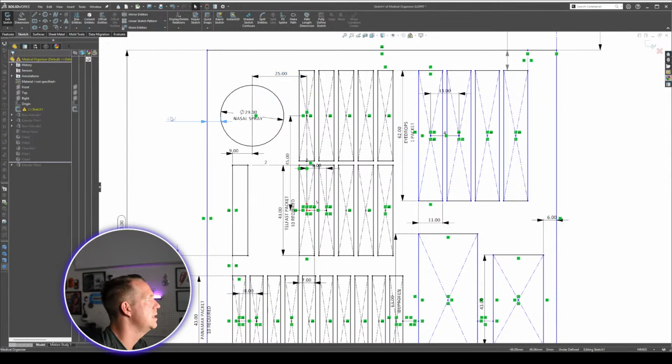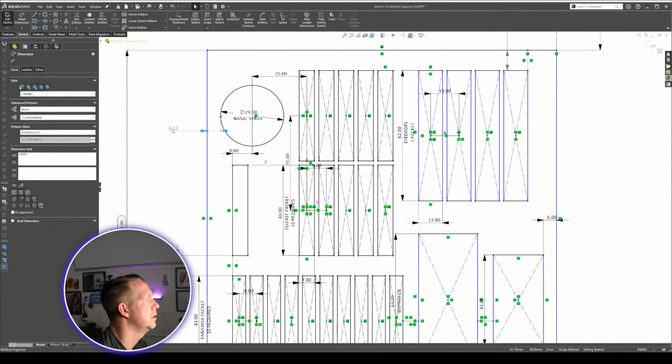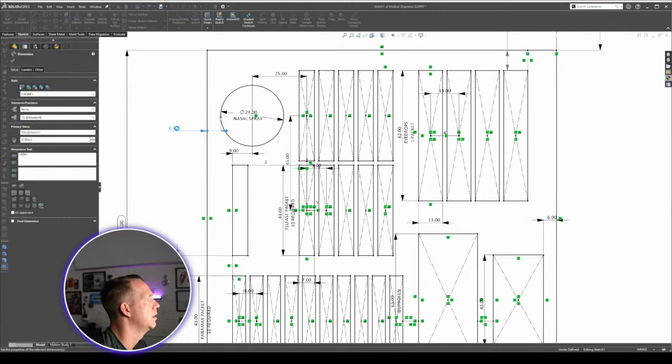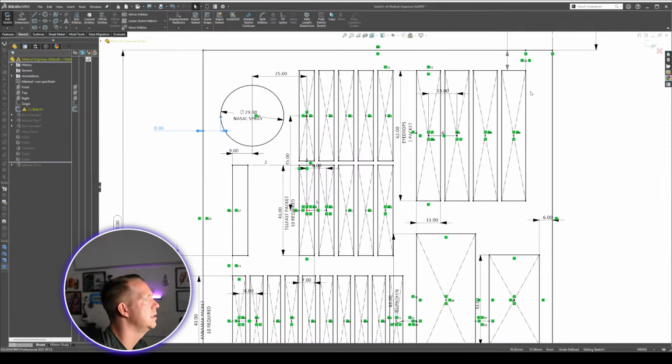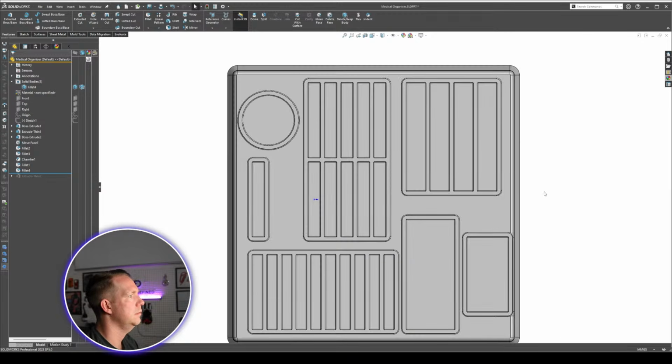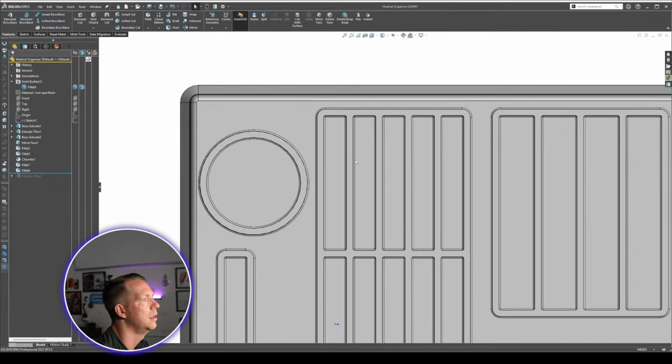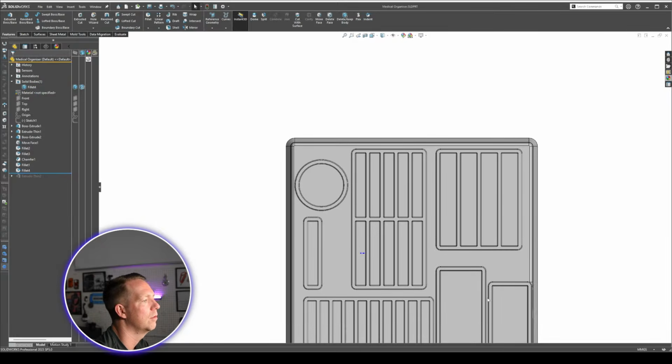Just temporarily made this driven. Now I'm going to uncheck that, make it driving, increase it. Now I think it didn't like it before, now it's okay. All right, as we gradually move that side forward, we've cleaned up this radius here. So that side is all looking all right.